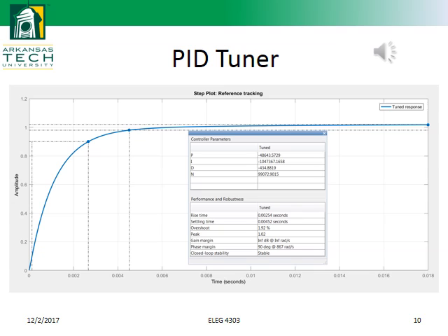By making adjustments within the PID tuner in MATLAB, we can adjust our P, I and D inputs to reach our goals of settling time and percent overshoot. We can see that we got settling time much lower than our target, and our percent overshoot is just under our 2%, which is what we're looking for.